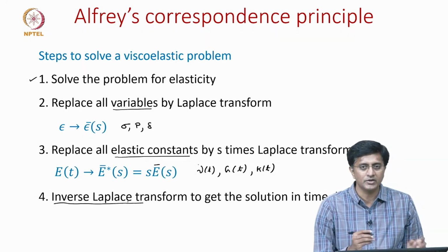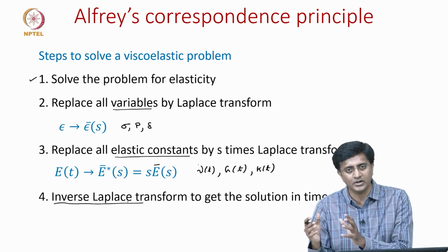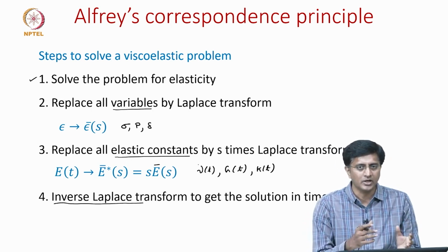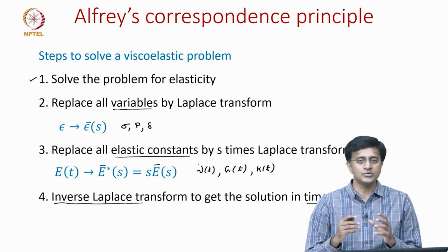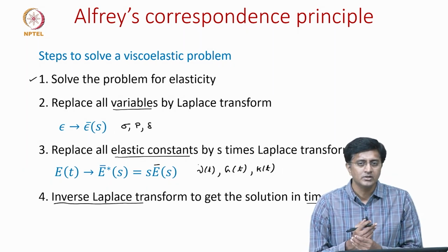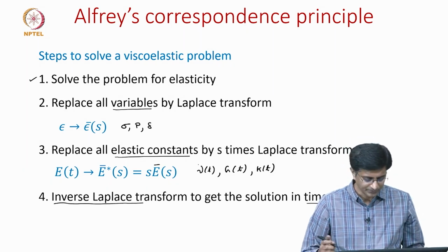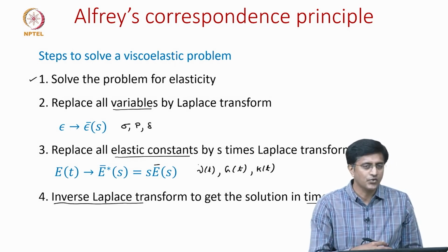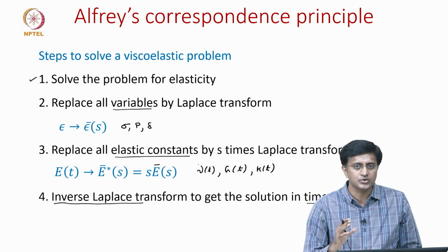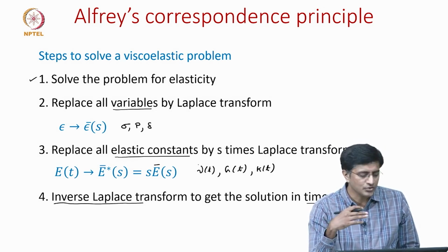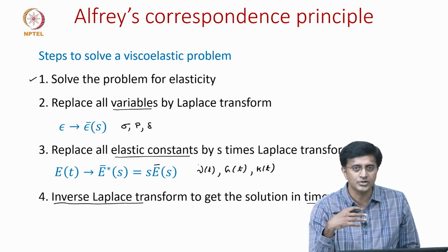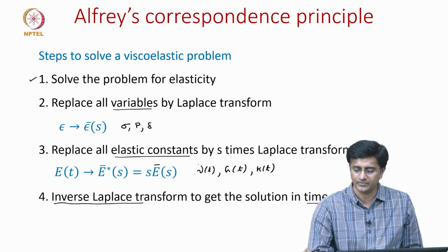Once we apply the inverse Laplace transform, we go from the Laplace domain to the time domain, and the solution we have is the solution we are looking for to the viscoelastic problem. So, if we follow these 4 steps, we should be able to solve most viscoelastic problems, at least those where we have solutions using elasticity.